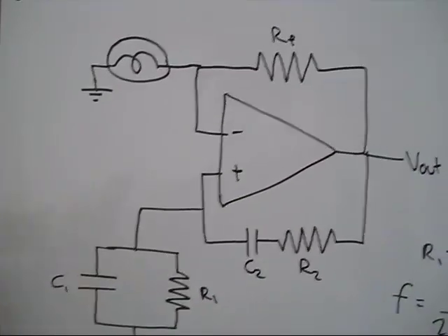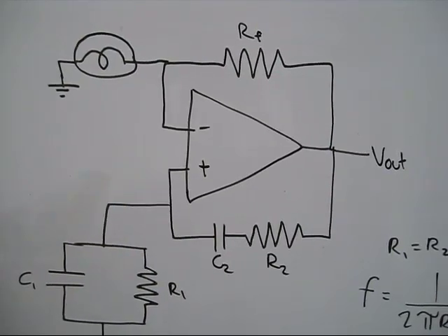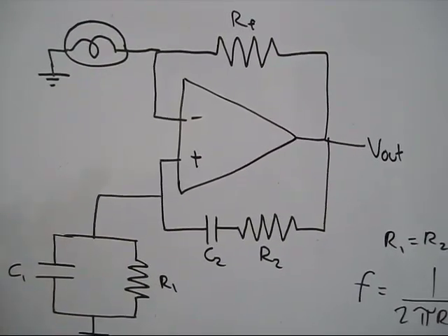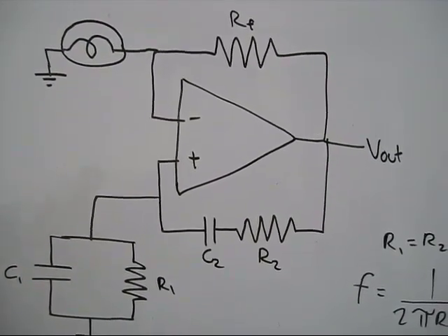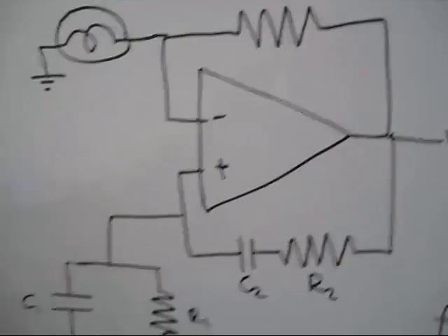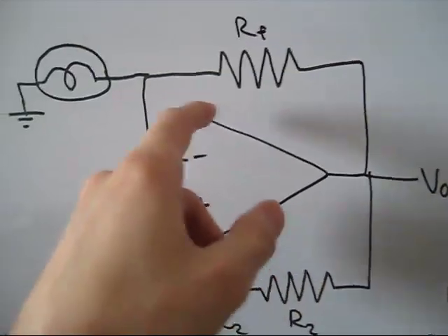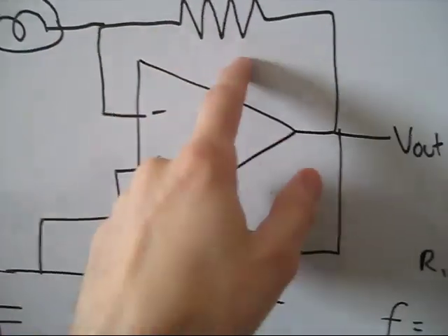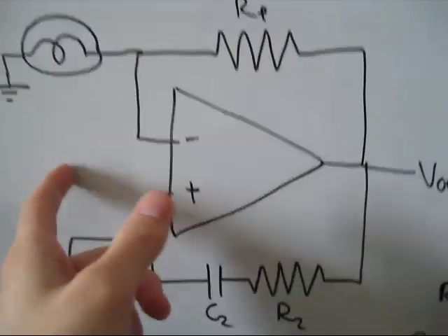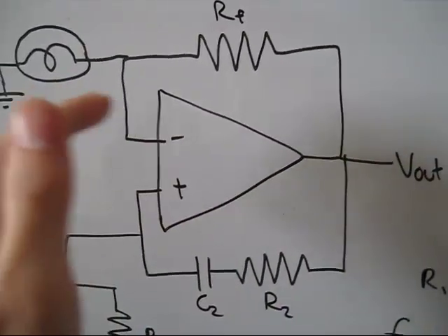What we've got here is actually the modern version of William Hewlett's 1939 Stanford University master's degree thesis, where he implemented this. Obviously back then they didn't have op-amps, so his implementation would have had tubes or whatnot. But this is the modernized version, and you can find the schematic on Wikipedia. So if we go over a little bit here, this is the actual bridge circuit part, and here we've got some gain control to actually make it oscillate. You're supposed to have unity gain for an oscillator, but if you don't have enough gain at startup, it'll never actually start oscillating because the zero output state is stable.